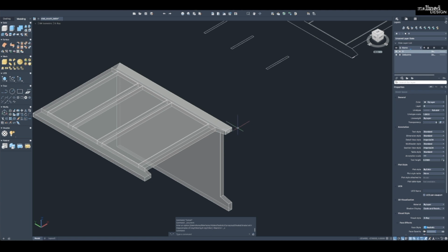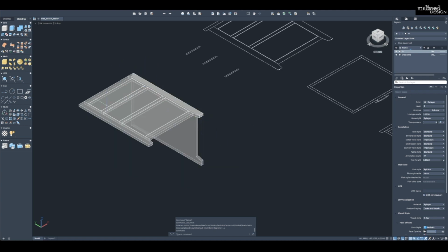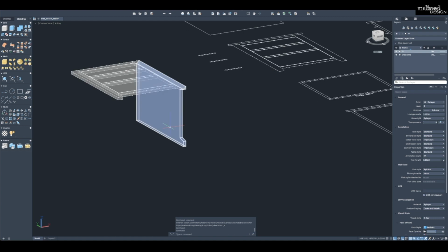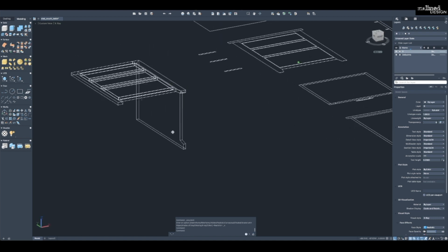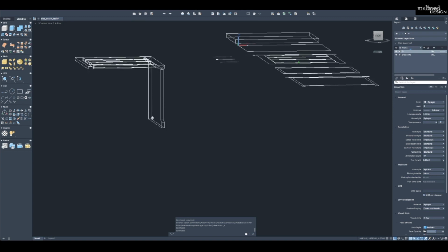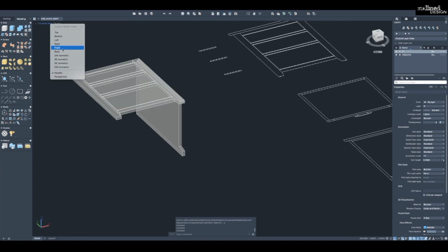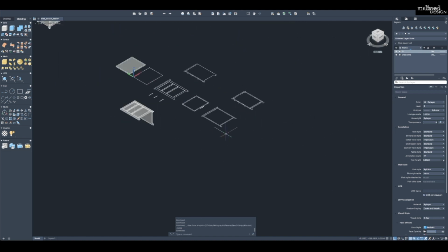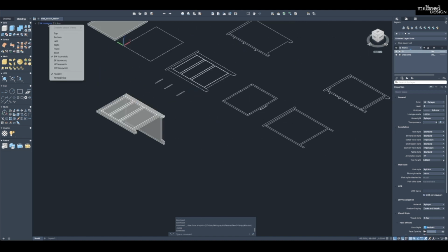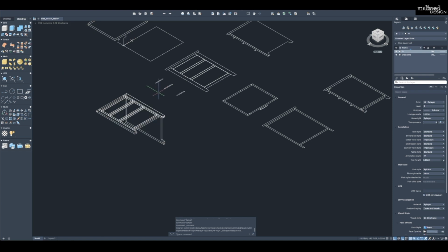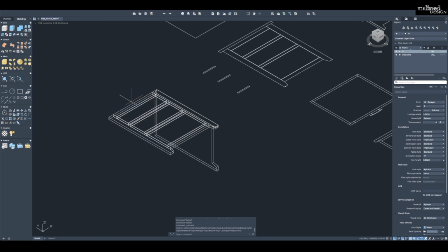Sometimes you will think you're lining something up, and then when you rotate it, so I'm holding the shift and center mouse button and I'm just rotating around so I can actually see that I did line those two components up. And then I'll switch back to Southwest. But again, I prefer to draw in just the 2D wire mode because for me it's faster. But whatever makes you see what you're actually doing is best.